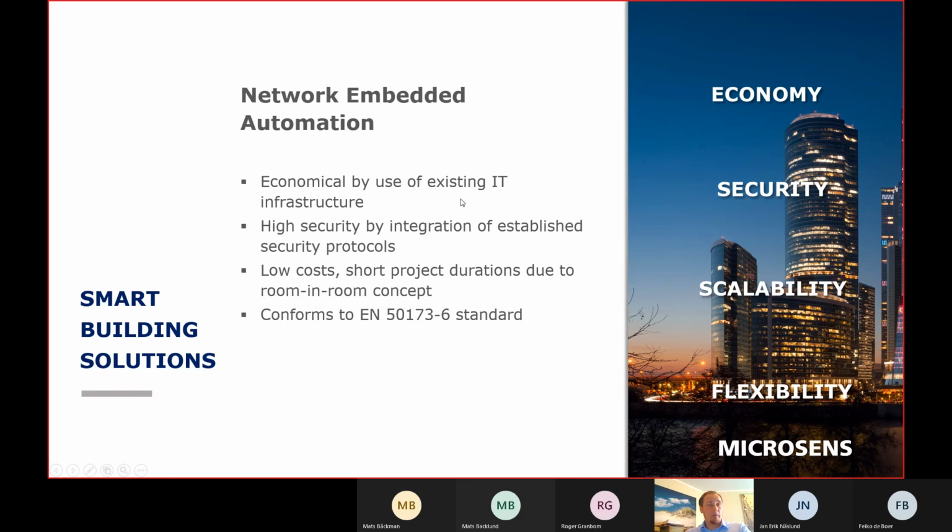The next part is only to have the IOs, which is the benefit of the PLC, that most of them bring the IOs directly connected next to them. So the problem is then we have to create a specially designed cabinet, which is configured to the specific demand of the project. So why not replace a fixed cabinet and bringing all of the wires from the floor to one centralized point? Also go the network way, because everywhere we have a network, so we can have a managed network, and we can create a network also for the IOs, so that my IO ports are not located inside of a cabinet in a central way. They are located everywhere where the field devices are located, like in the ceiling inside of a room, like in the technical room for the air handling unit. And we don't need these specially designed cabinets.